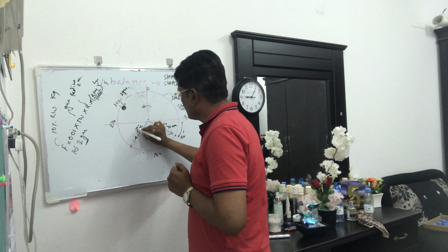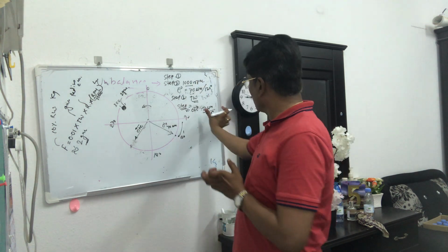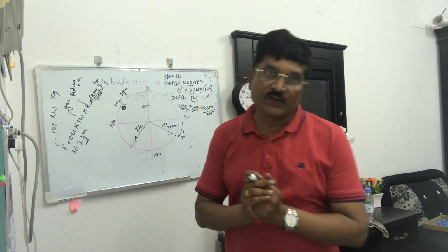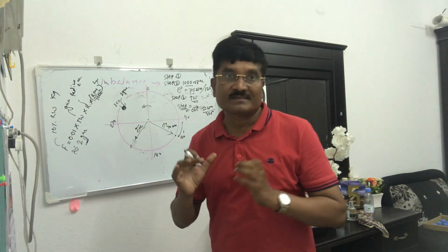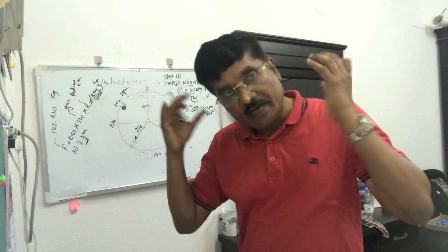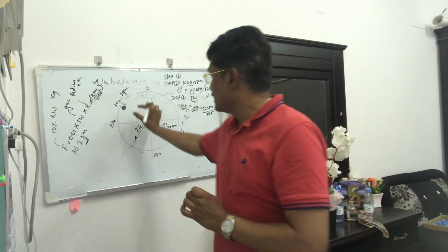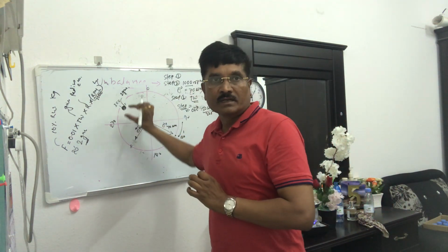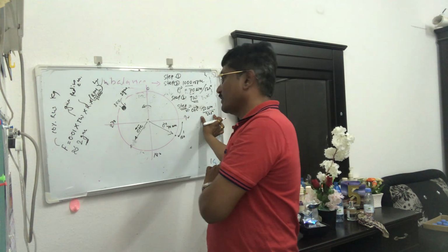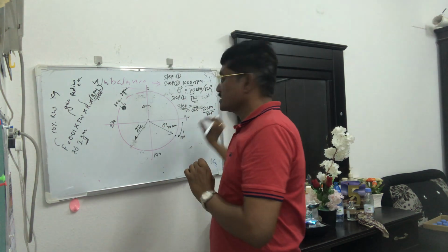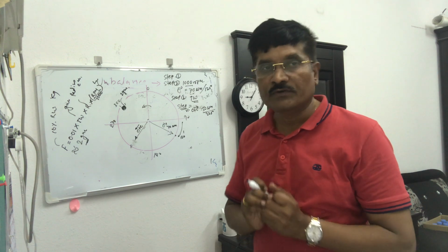Why am I telling this O plus C? Because whatever vibration we got now is the effect of the original unbalance available in that machine or rotor, plus whatever trial weight we added here. The combined effect came here, about 50 microns at 225 degrees.